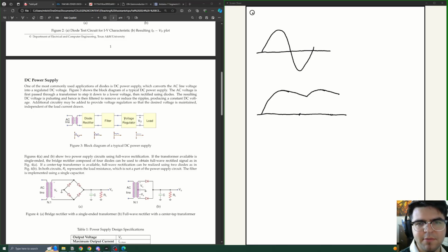So a regulator is an even more precision device. It's going to take a semi-consistent input like this, which is hovering around some voltage level, but we don't want to deal with these big peaks. A voltage regulator, for example a low dropout regulator, an LDO, or a buck boost converter like one that you might be studying in ECEN 340, will take this more inconsistent voltage and flatten it out as much as possible. So it might be a little bit of oscillations like this,